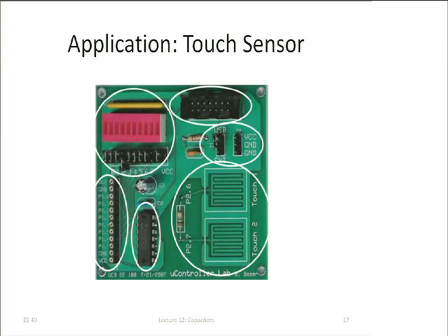On your smartphone, there are invisible traces, invisible wires on the screen. You can't see them because it's a material that is conductive called ITO, but it's transparent, so you don't see it. And what you're actually doing is putting your finger there, and because your finger is mostly water, it changes the capacitance, and then we can detect where your finger is.